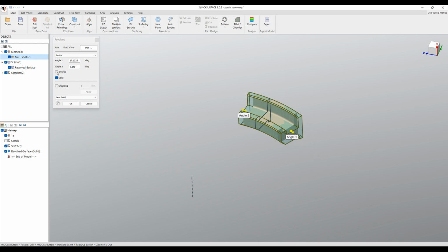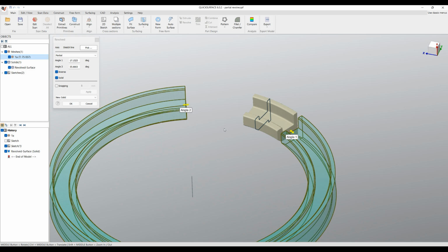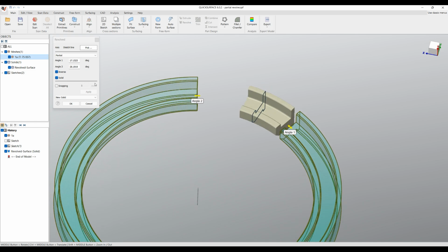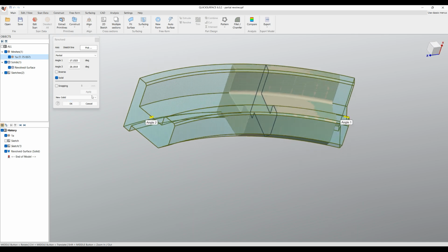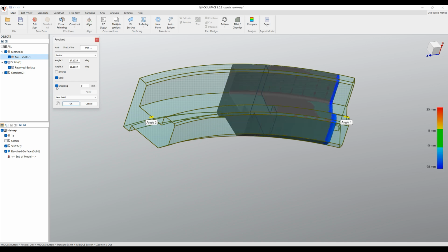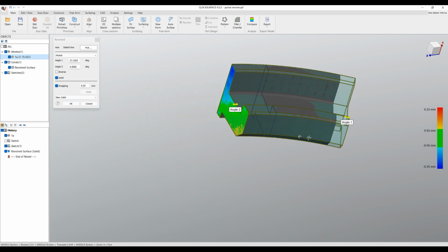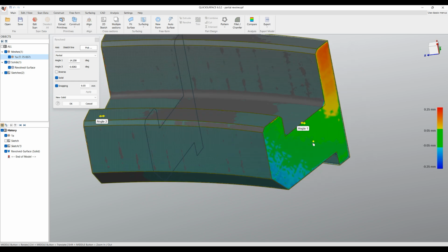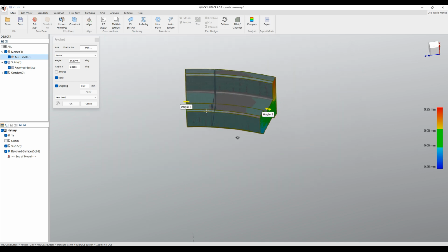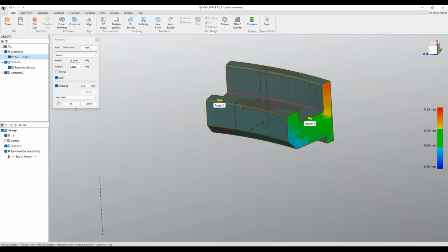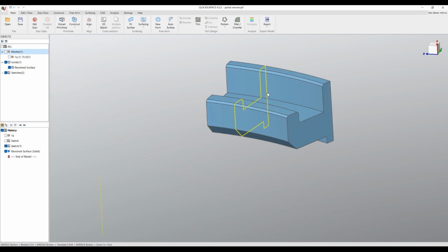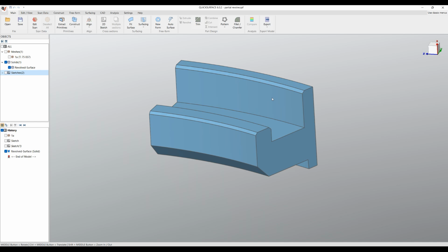In some cases you may need to inverse, so you can create the other side of the shape, so we also have this control. The interesting point here is that we also support snapping. If you just click on the snapping 0.05 millimeters, let's say this, then when I drag, it just picks a point from the mesh, and then you can choose where it needs to be. Of course, you have full control over the other angles as well, so you can get the best possible result. So that's the new thing about the partial revolve.